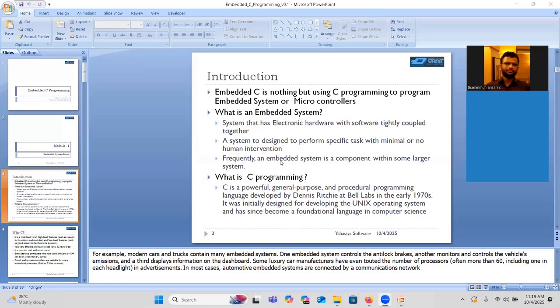Similarly, these telltales are nothing but LEDs glowing behind an annunciator. Behind an image, they will glow LEDs of different colors. These LEDs are controlled via port IO. Via port IO, we can configure them as output pins. When we want to glow that particular LED, we can set that pin to 1 or 0. That will make the LED glow, which will make the annunciator glow so that the driver can see the telltale.